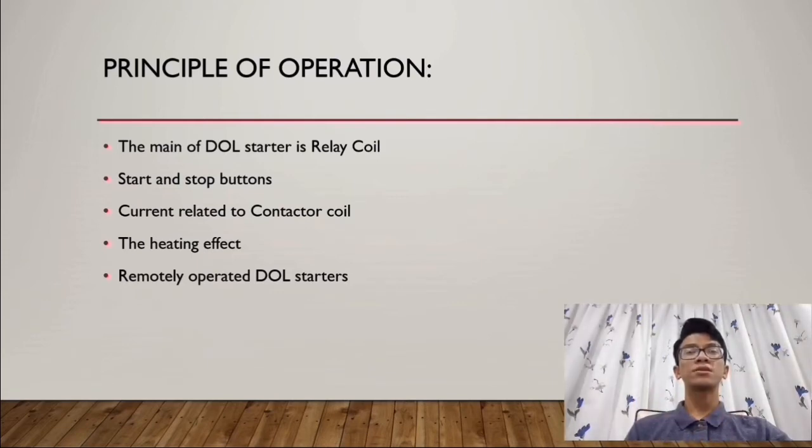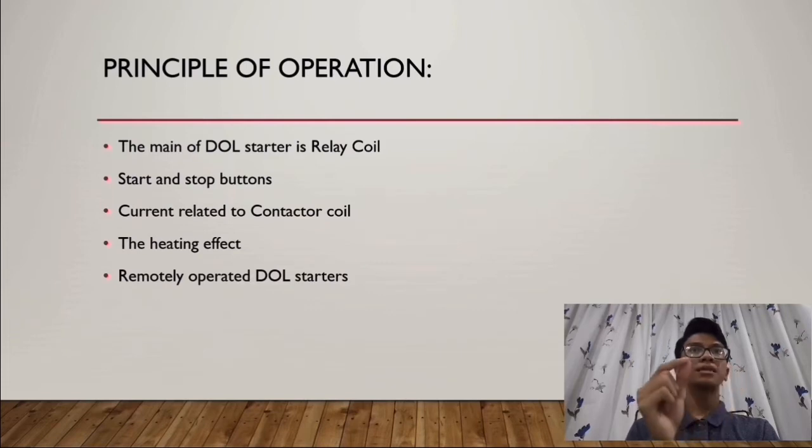In the photo we can see this in the circuit. So next is the start and stop button. The direct online starter wiring refers to the start and stop buttons between the main supply terminal and the motor terminal. The starter main terminals are connected with the terminals of the three-phase motor power supply, and the control circuit is energized.